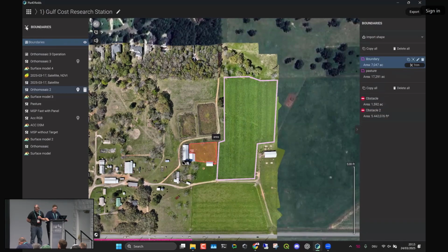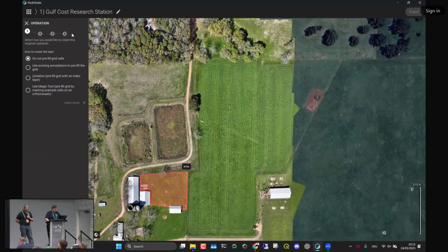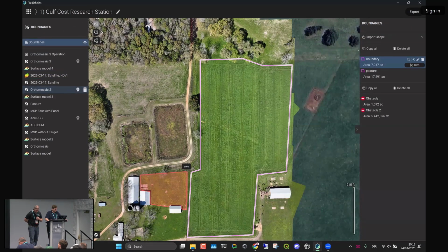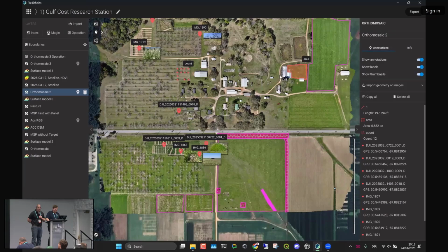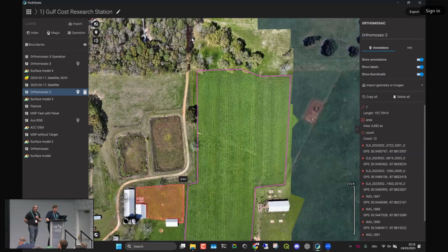And now we want to do a zonation, right? We want to see where this pasture grows well, where it grows not so well. So we go back into operations. Can we make an index map of the multispectral? Oh, let's just do it with an RGB. Maybe I don't have the money to buy a multispectral. Okay, let's do that. But first I think we should trim, because we don't want to process the whole data set, so we only want to process the AOI of our actual object.